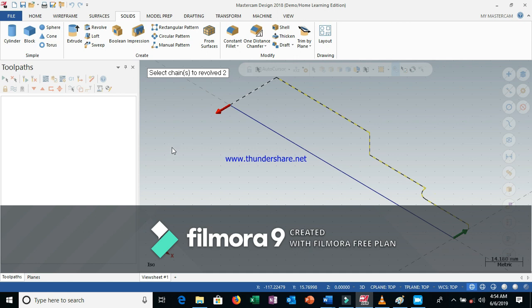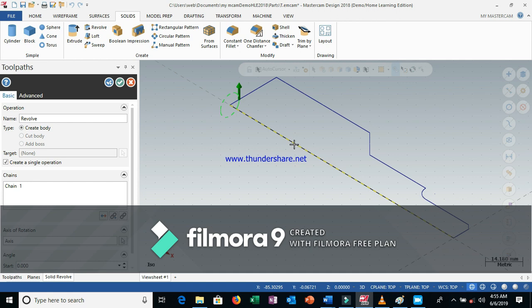Now we have to select the axis, to where it will revolve. Okay. We have to select the axis to where it revolves. Just go to, yes, see it is showing even the symbol here. So select the line to be used as the axis of rotation. Just select this axis. Just select this. It will blink, okay? Just select it. So now it will revolve. Yes, done.